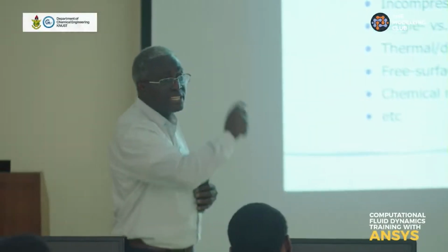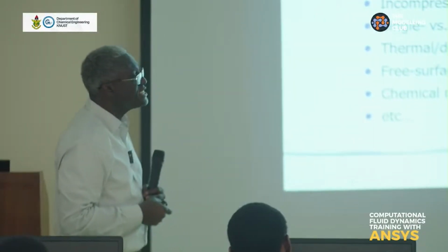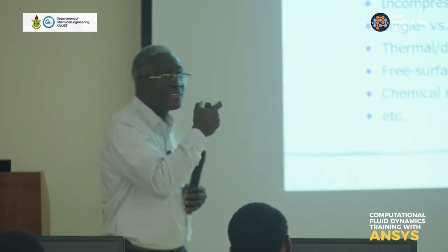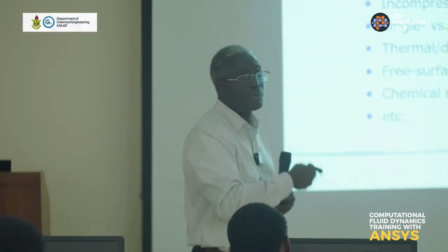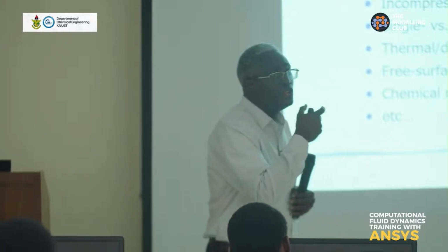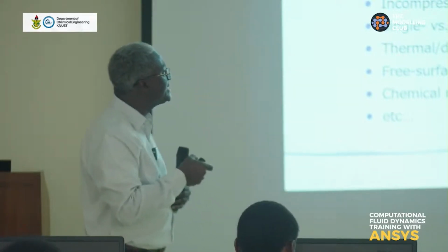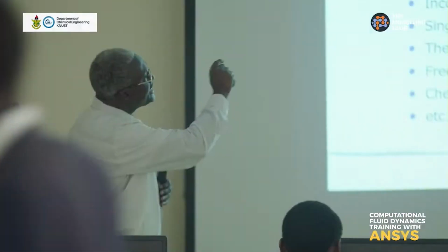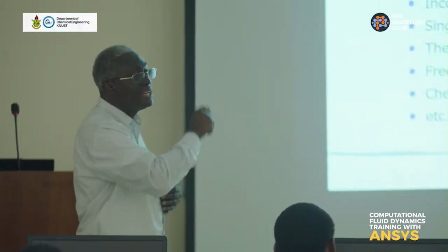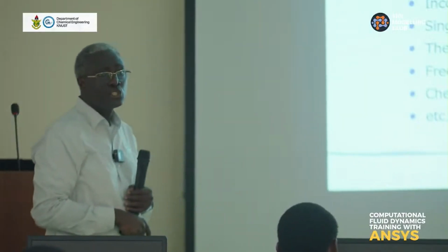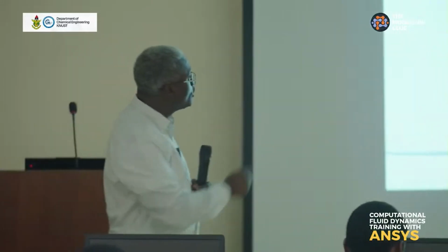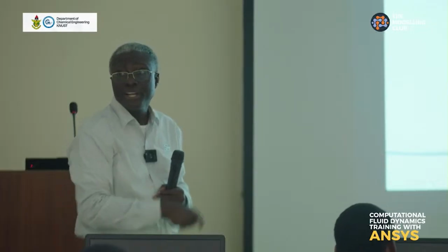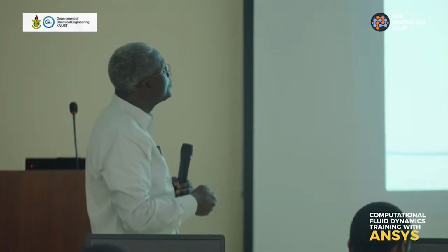After I have determined the mathematical formulation representing the physical system, I need certain simplifications in order to solve the problem. Knowing those simplifications helps me to distinguish between the different categories or the criteria that have to be applied in the solution of that CFD problem. And so these are just examples of some of the simplifications or the criteria in classifying CFD problems.